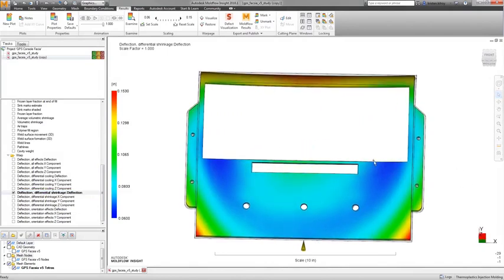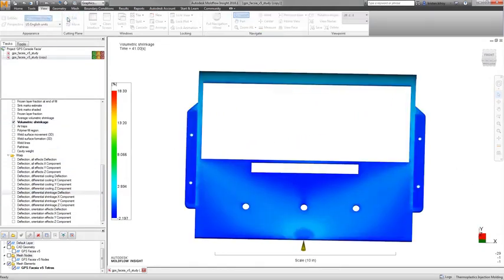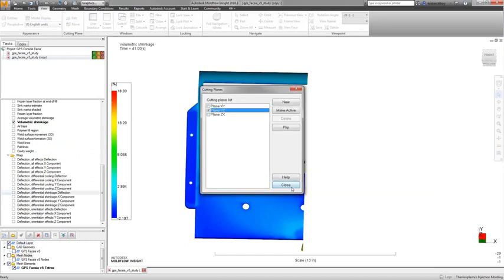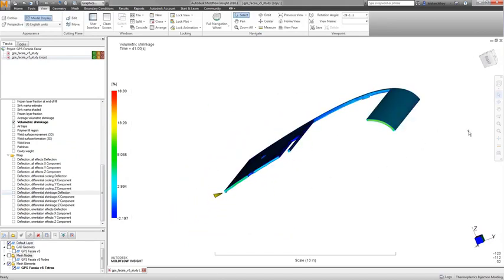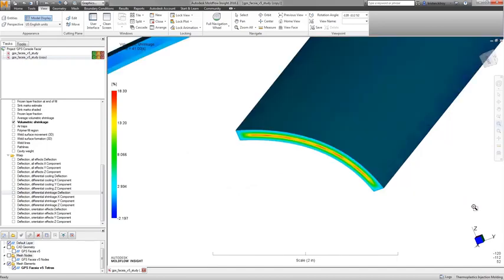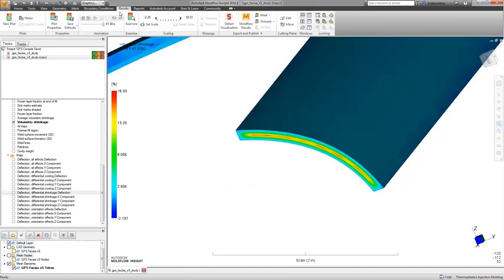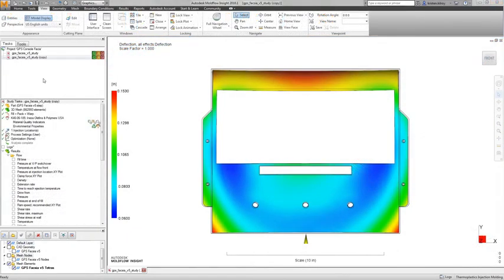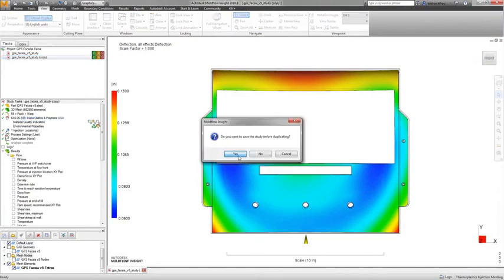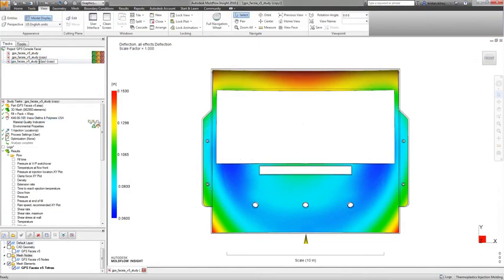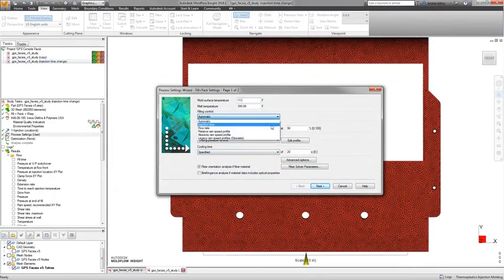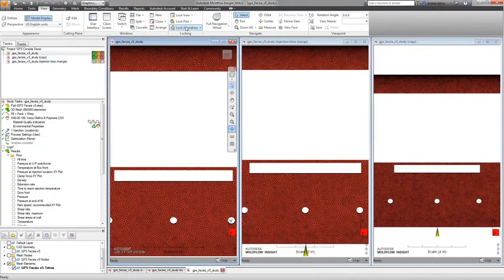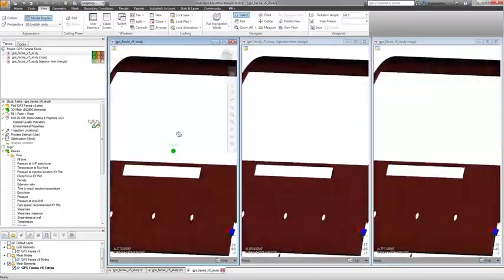Understanding this, considerations such as inserting additional cooling to aid in uniform shrinkage, increasing injection time to reduce excess material shearing, or changing the gating location may help to reduce the overall deflection. Understanding the cause helps to work backward and identify ways to reduce either overall or warp in specific locations. With any iterative process, changing one thing can result in other changes. So continuing the process of reviewing results and making small changes until an acceptable deflection is achieved is crucial.